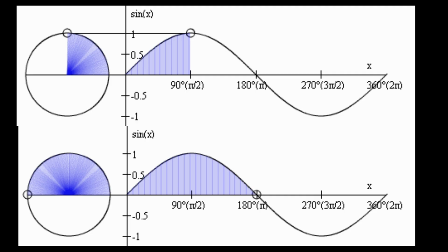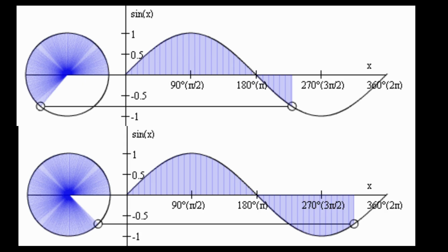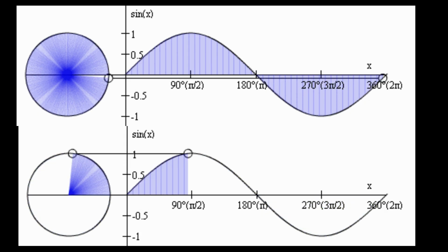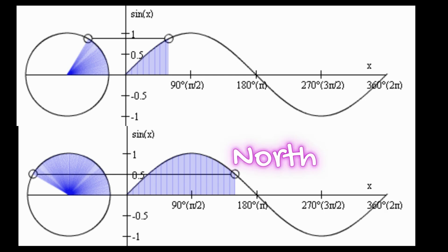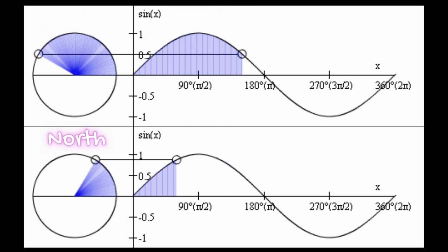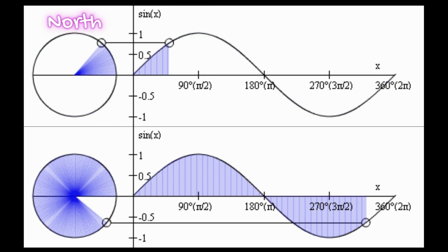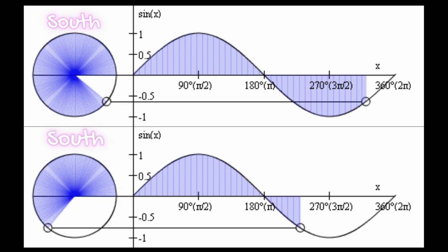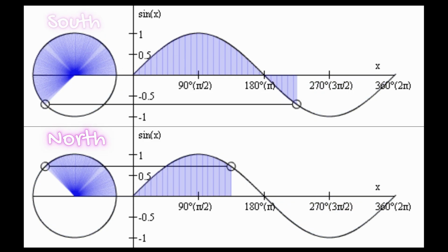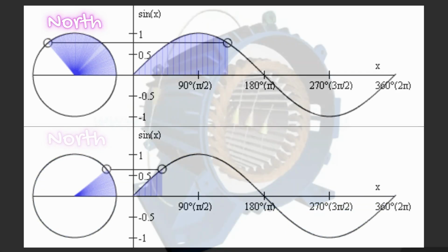Now what this does is that the two sine waves that go through the windings in the motor are now no longer 180 degrees apart. They are now 60 to 90 degrees apart. Now as both currents flow through both windings of the motor, you have one current that's building up a northern magnetic field, and the other one, because it's only 90 degrees behind, is also going to start building up a magnetic field of the same polarity. So we'll have north, north, south, south, north, north, south, south, and they're offset just enough that it creates a rotating magnetic field in a circular pattern.